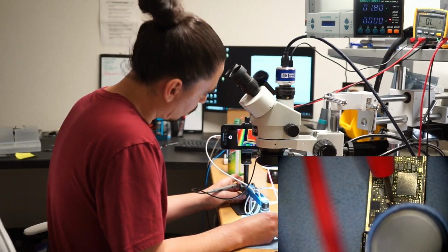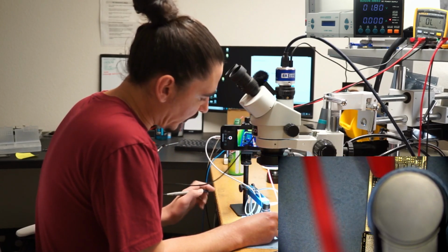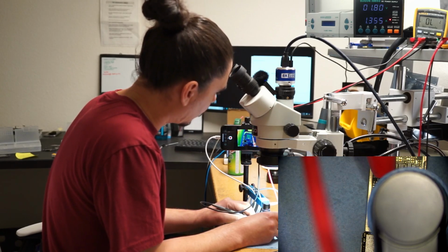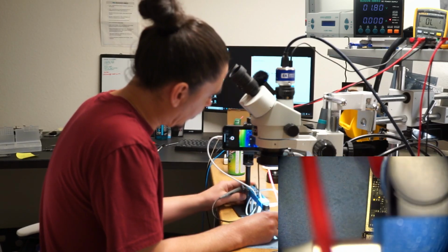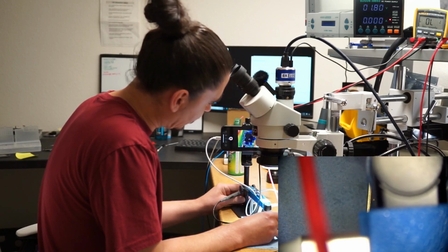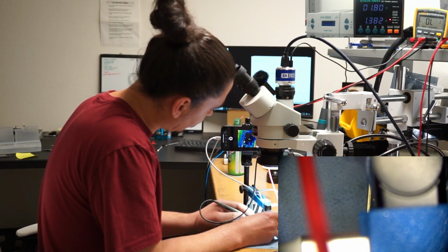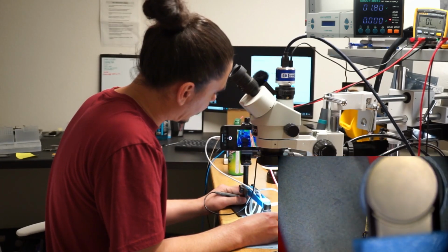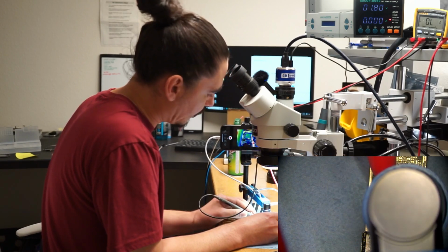So I'm not seeing any heat above the charging IC. So let's see if we can find it somewhere else. I'll try to overlay my thermal cam here so you can see it when I find the actual culprit. Still not seeing any heat. I'm not seeing anything. And that's a bad sign. This is likely going to be RAM if heat shows up nowhere else.